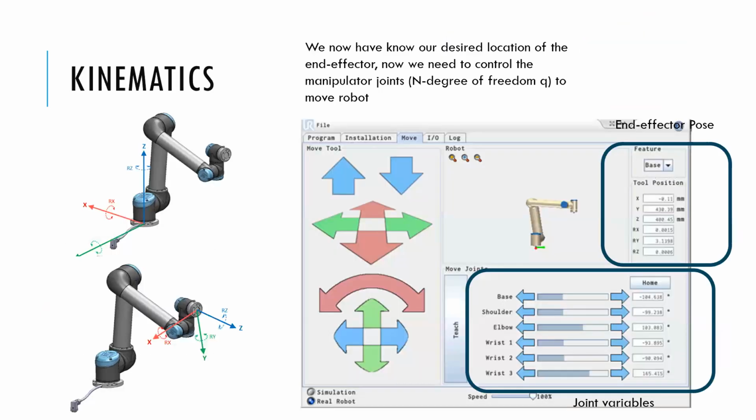When you move the robot using the pendant, it's going to automatically compute, and that's what it's doing in the background, computing its forward and inverse kinematics, and you will see it on the pendant itself. So most robot systems you can just look at, but the actual mathematics behind it is what we're doing. That is the linear algebra that I showed you before.